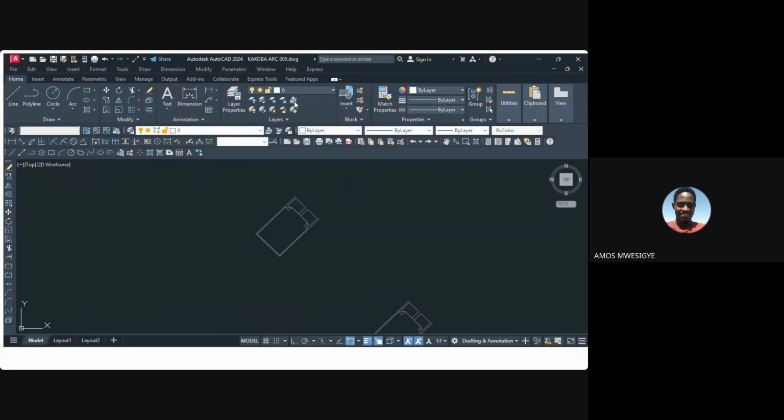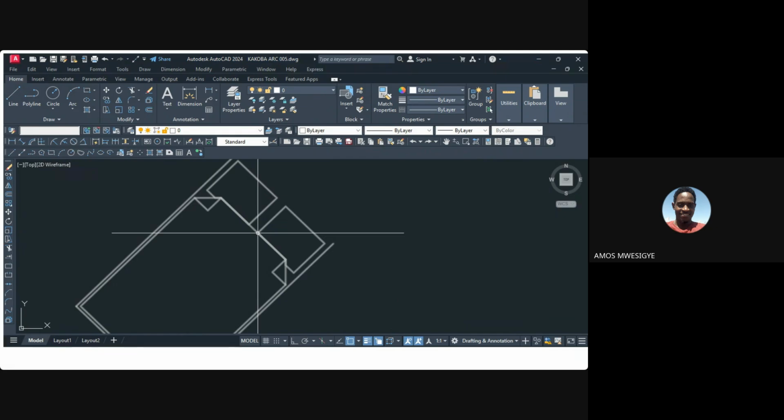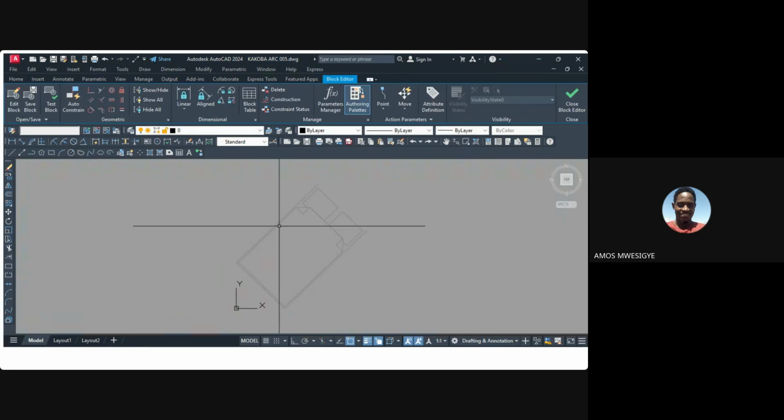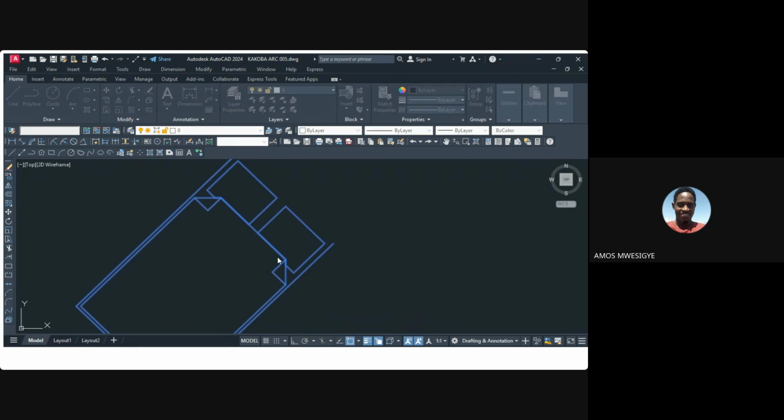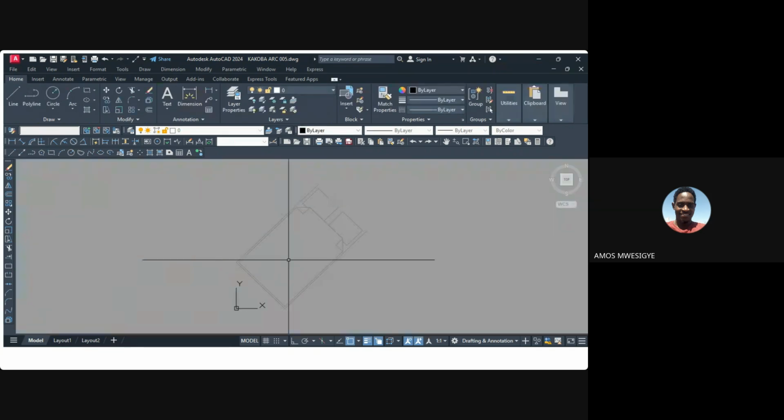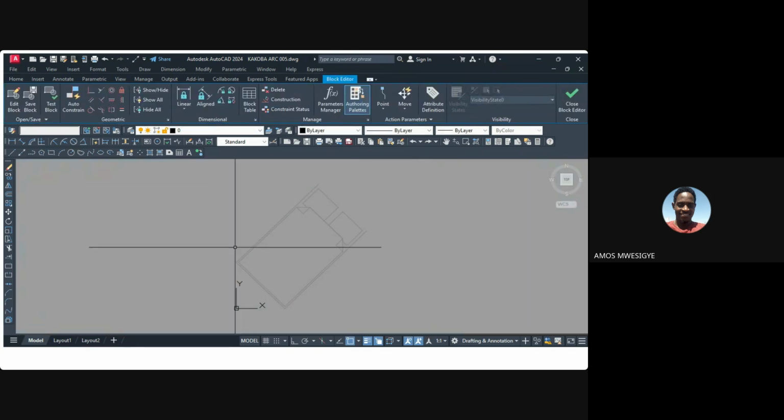If I put it to layer 0, and I want to delete the rest of the layers from the working space, the layers under this block... let me go into this block to really see the items that make up that block. If I select this and go inside that block, have you seen how we've gone into that block? Let me close again, I show you. I've double clicked here. It brings the description. So you go to OK. So it brings you to the block itself.